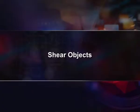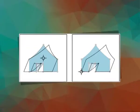object. Shear objects. Shearing an object slants or skews the object along the horizontal or vertical axis or a specified angle that's relative to a specified axis using the shear tool. Objects shear relative to a reference point which varies depending on the shearing method you choose and can be changed for most shearing methods. You can lock one dimension of an object as you shear it, and you can shear one object or multiple objects simultaneously.